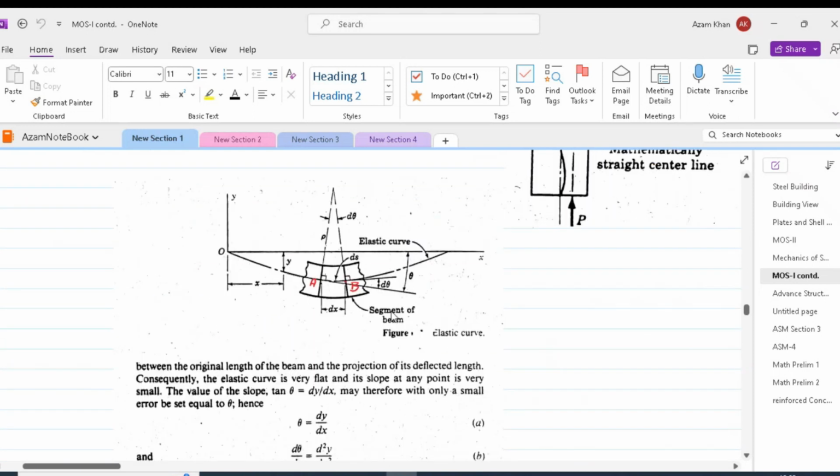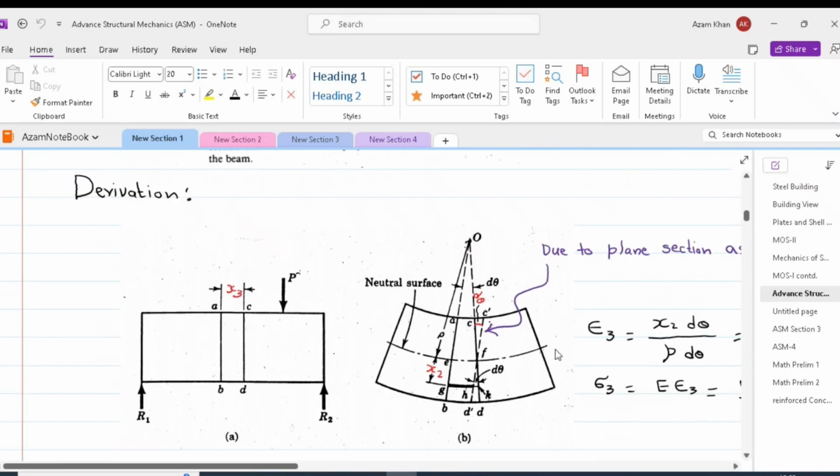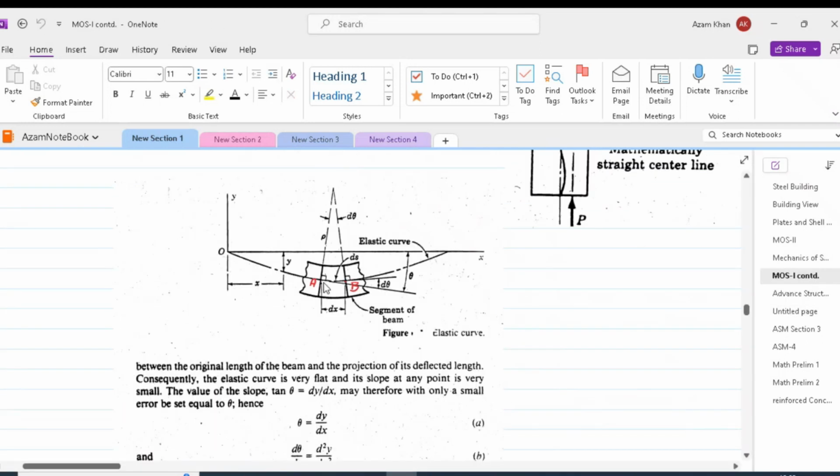So we consider the same beam as discussed, subject to some loading. If we take 2 points which are very close to one another, draw tangents at those 2 points shown as A and B, and then draw normals to those tangents, they should meet at a point, provided that the beam has deflected.